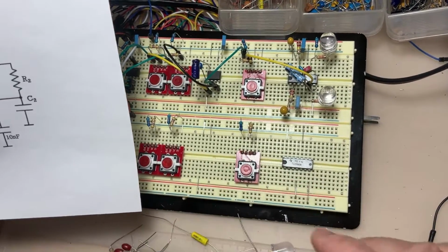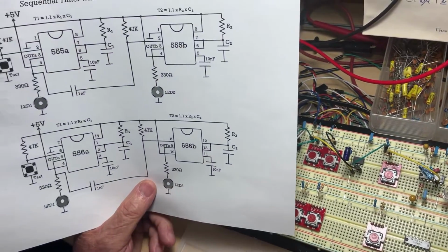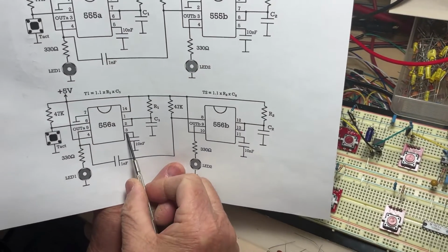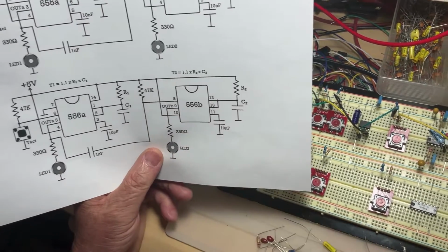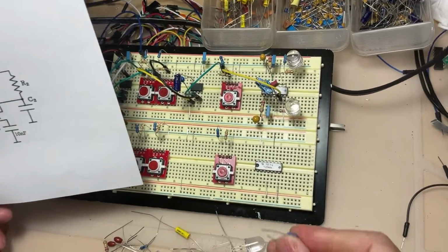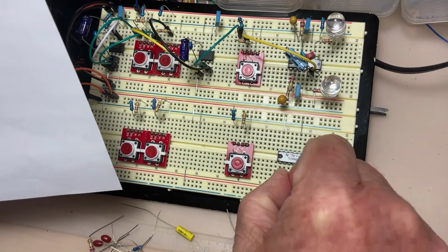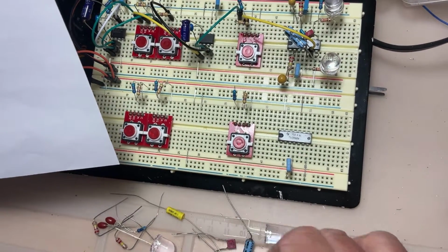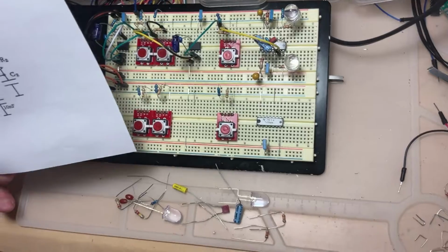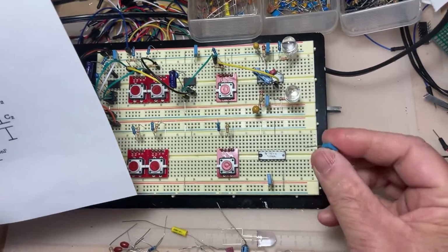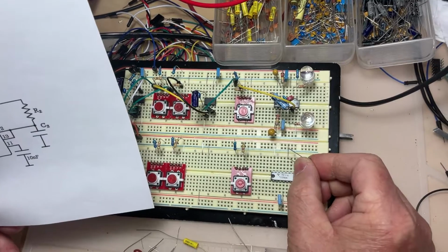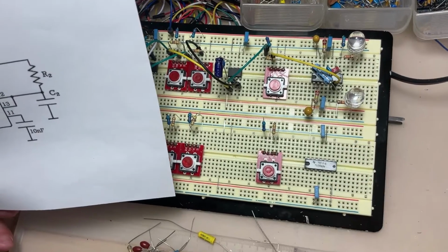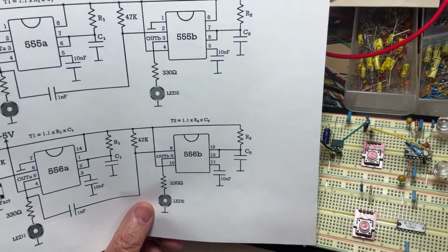I'm going to decouple the pin number 5, the voltage control for the 555. Now I have the pin number 3 for the first half and the pin number 11. So for these two, for the pin 3, take a look what I'm doing. I'm just connecting a 10 nanofarad capacitor. So this little blue body is a 10 nanofarad capacitor. I'm going to connect it exactly on the pin 3 and on the pin 11 to the ground. So I decouple the two voltage control terminals because I don't need them anymore.